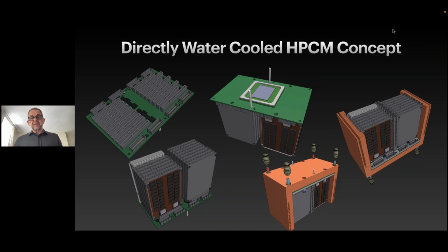And so the HPCM was inspired by that, but instead of having the mezzanine connectors on the bottom of the board connecting to a host motherboard, we replaced it with media interconnect and cable interconnect on the back. So we actually removed the motherboard altogether. In the top left, you can see there are 16 EDSFF connectors, which is becoming very popular now for SSDs and CXL.mem, and the NIC 3.0 standard also uses these same connectors. So we've got some normalization going on here where we can plug these different media and IO modules in. But this is coupling these connectors really tightly.